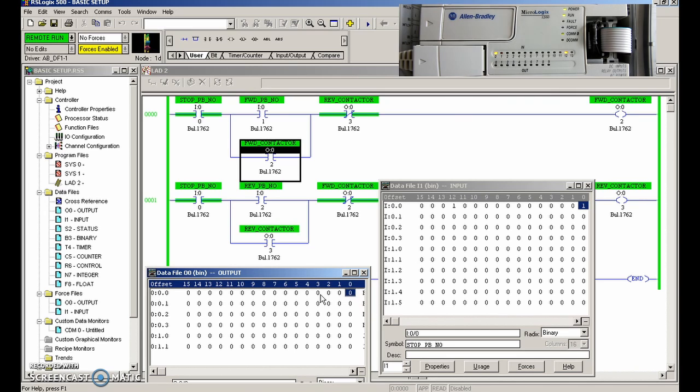Beautiful. And that's basically it. I mean, the only issue is that while it's running, I have no way to know whether that contactor has actually pulled in, right? I don't have anything out in the field that's sending another signal in. Like I can physically push the forward contactor in right now, and you can see that light right there, input number 5 is changing, but I don't have input number 5 in my program. So I don't see anything, right?